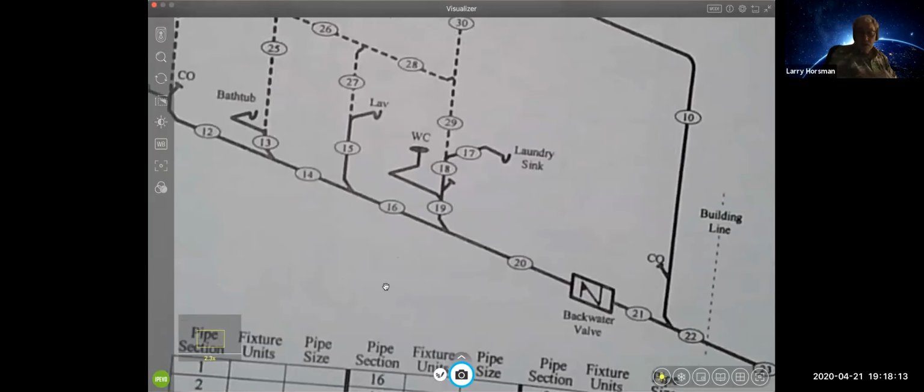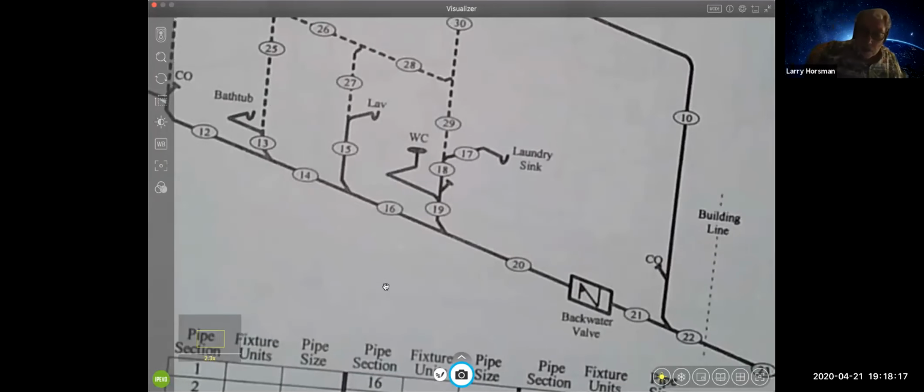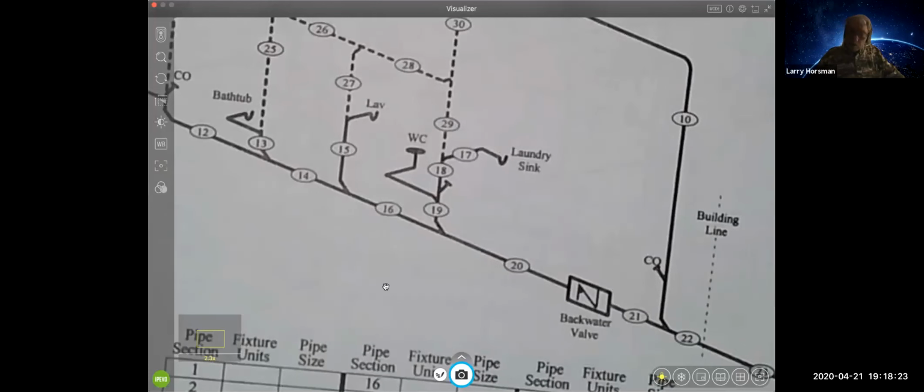And so the lower floor in this case is below the sewer out in the street, or at least below the manhole rim. What happens is, you may be below or above the sewer. However, you may not be below the manhole. As long as you're above the sewer, sewage under normal circumstances will flow.